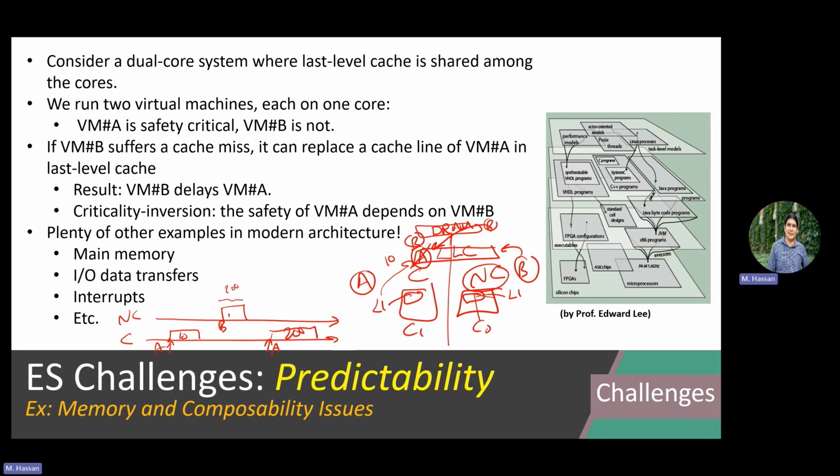Yeah, that's an excellent question. How does it make a difference? What really happened here? To know this, assume that the non-critical task did not exist. What was going to happen? It will stay 10, right? So when you calculate your timing, remember, in critical tasks, we care that your execution time must really meet your deadline, right? Now, to be able to meet my deadline, I need to calculate my execution time and ensure it's less than my deadline, right? Now, without the existence of the non-critical task, how do we calculate this? I have cache hits, cache misses, I add things up, I'm safe, I'm good. But there is a non-critical task competing with you, turning some of your cache hits into misses. How does it impact things? It increases your execution time. Exactly, because right now, I didn't really get A until after waiting for 200 cycles, right?